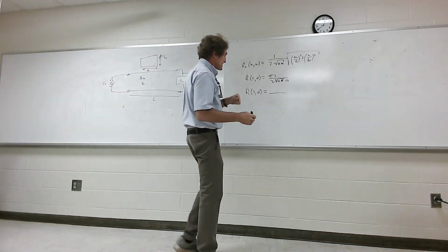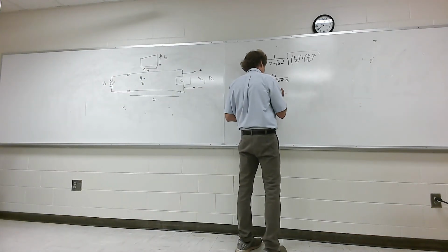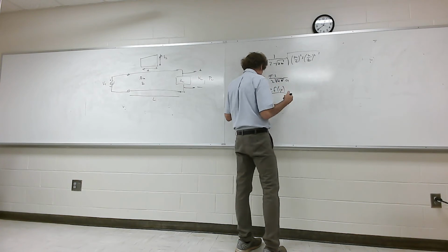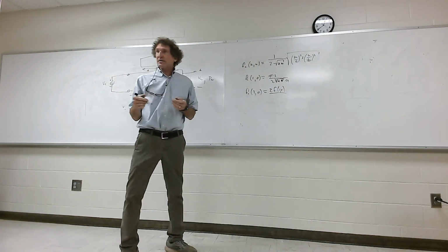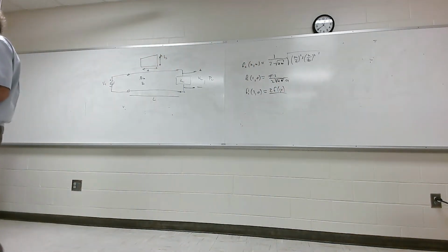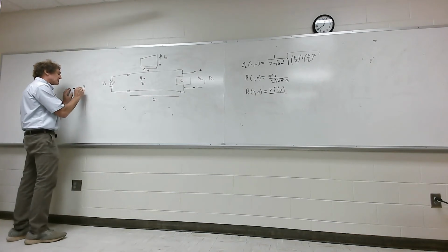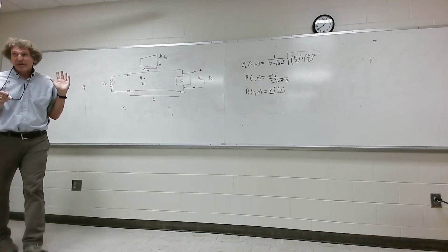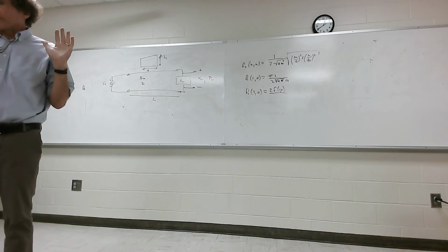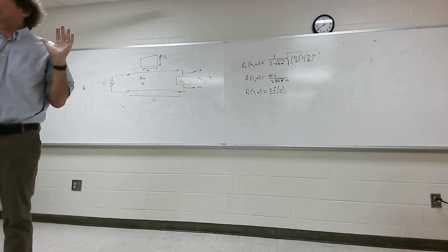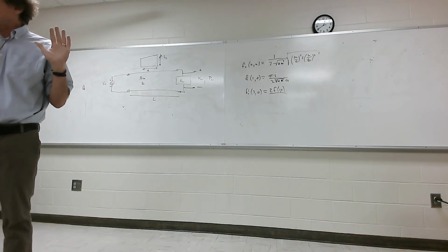So these are usually the way the modes develop. You find out what that is, that's just twice the f10 mode. And then you find the next mode, right? Because it could be the 11, or it could be the 01 mode, pardon, the 01 mode. Y'all follow me on this one, class? So you can do this and you figure out what the lowest modes are. And hopefully, this frequency f0 lies between the 10 and the 20 mode. Because if it's below the 10 mode, nothing propagates. Y'all follow me on that?